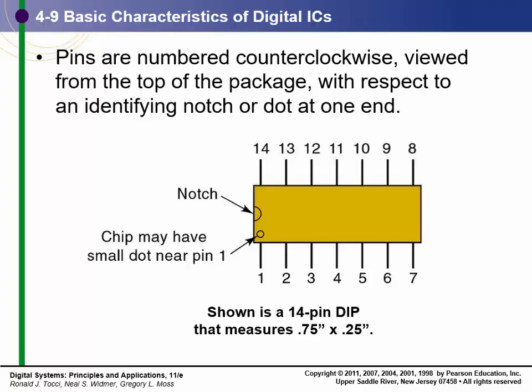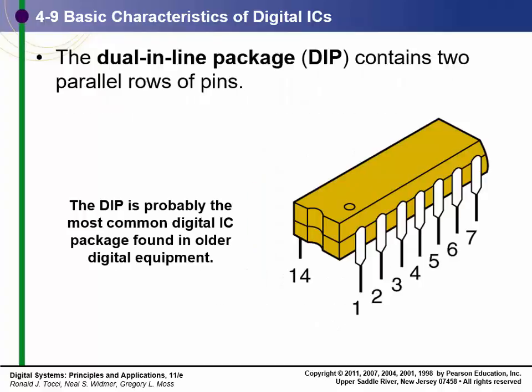And one of the things to point out is this package right here. That's a through hole. Through hole means that these pins right here go through the circuit board and they're soldered on the back side. Now, if you're using the prototyping board like you might have used for your electronics courses, you push those into the board, right? And then you put the wires to connect it to other circuits. Through-hole technology for most modern electronics is going away.